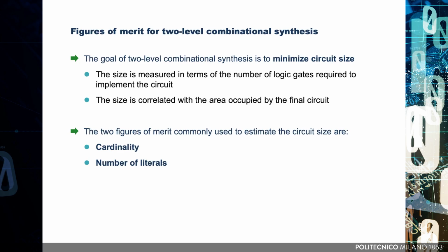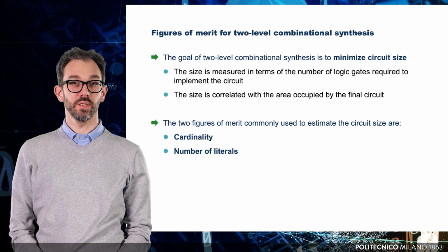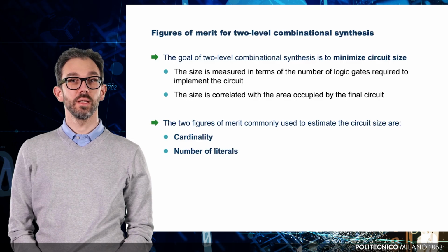In two-level logic synthesis, we do not usually consider latency, because assuming a delay model where each n-input gate has the same delay, a two-level circuit will always have a fixed overall latency of 2. Nonetheless, if we adopt a more fine-grained delay model that also accounts for the number of inputs to each gate, it can be shown that, since the reference model maintains 2 logic levels, minimizing the circuit size also positively impacts its latency.